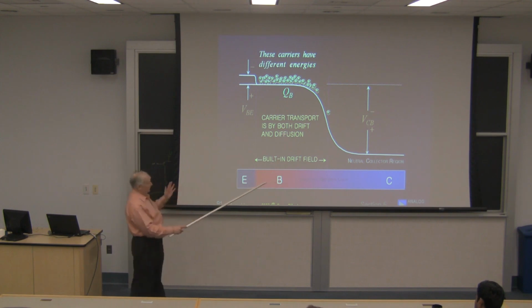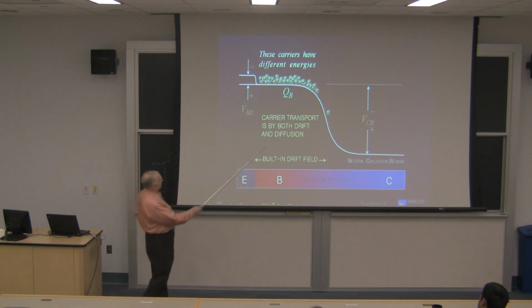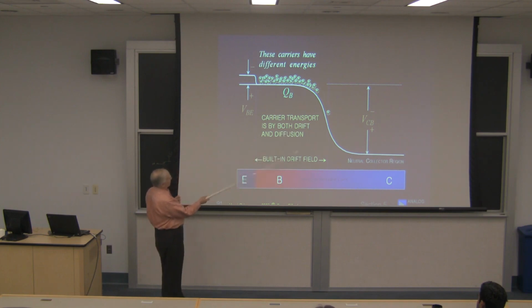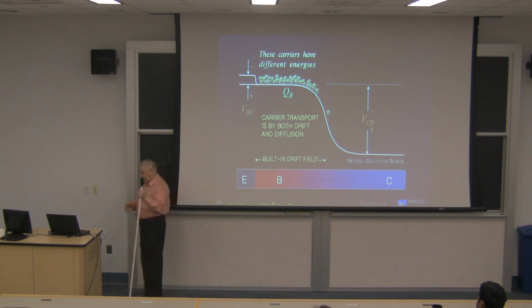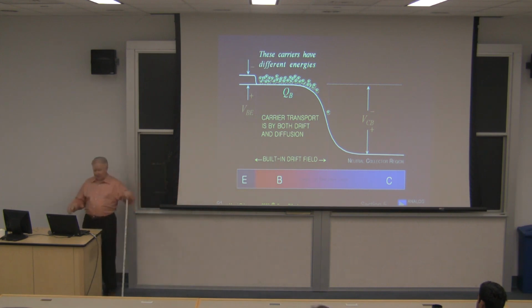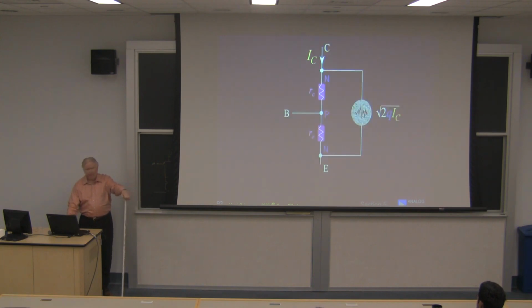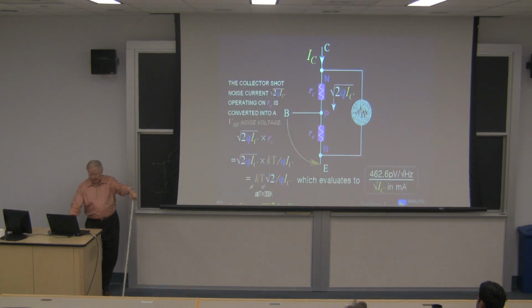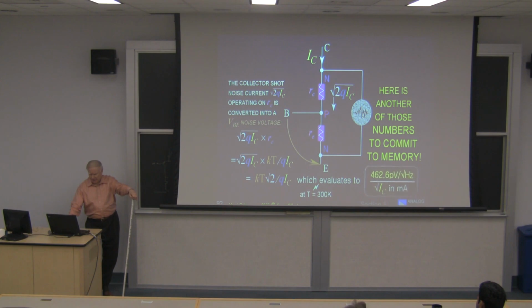In an older style monolithic transistor, it would be almost totally by diffusion. But there's here a drift flow as well. So you can see that the point I'm making is, it's just like our flock of geese. There's a drift aspect to this current and a diffusion. You can begin to see why the intractability of so-called thermal noise and shot noise gets to be a little bit fuzzy. Now, I think I'm not going to go much further, because this really begins a long litany about how to calculate noise in all kinds of situations.